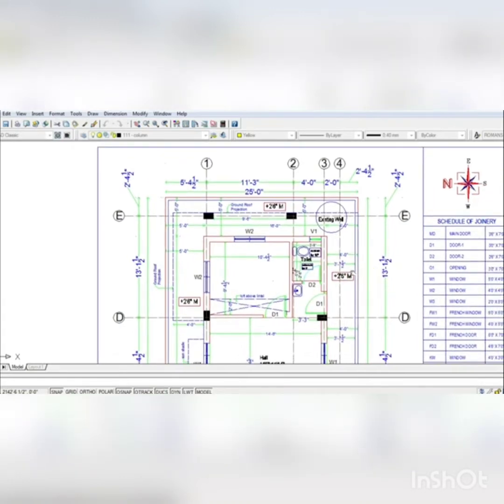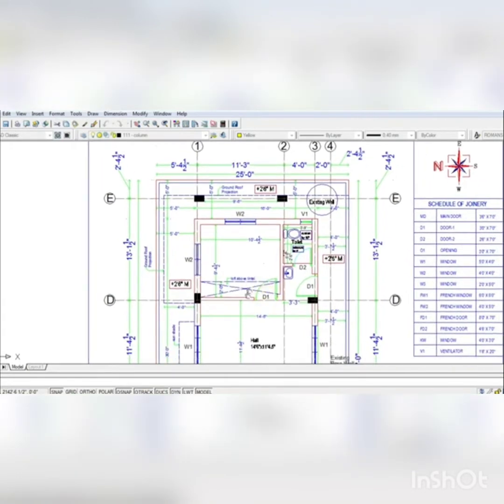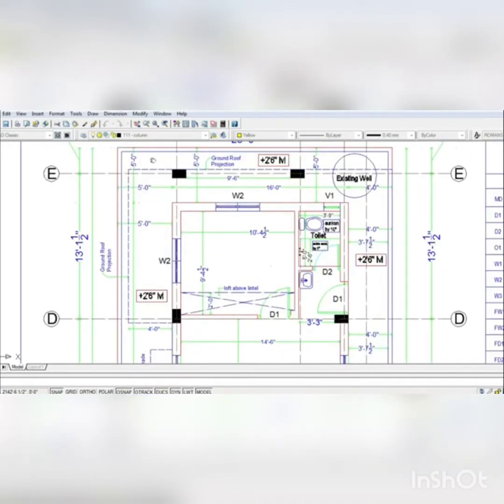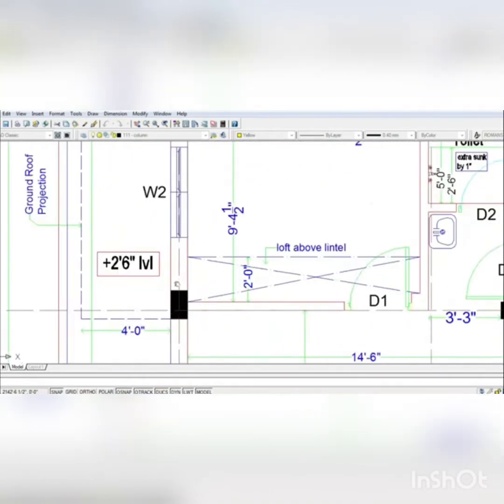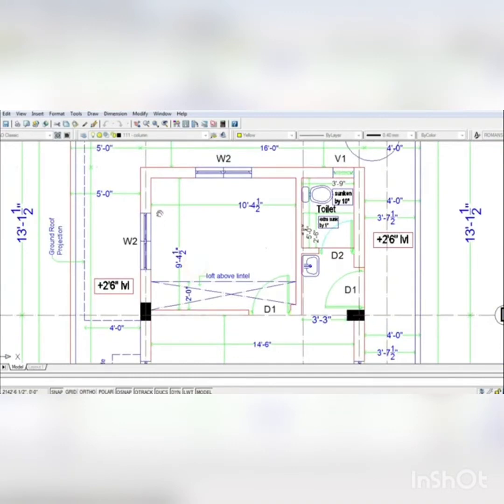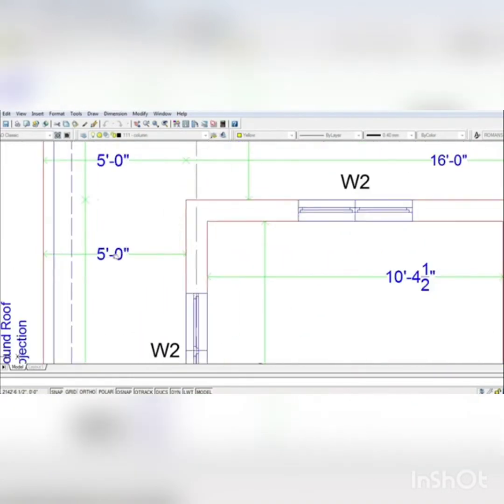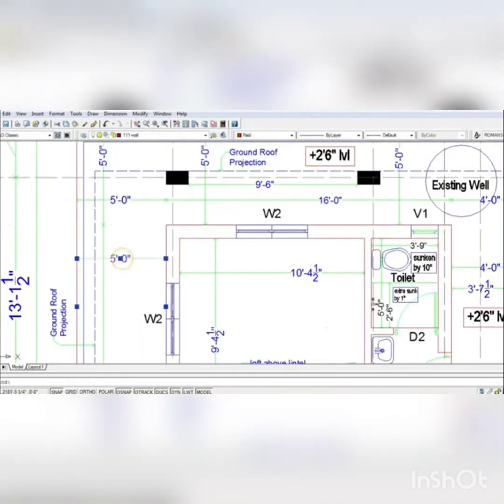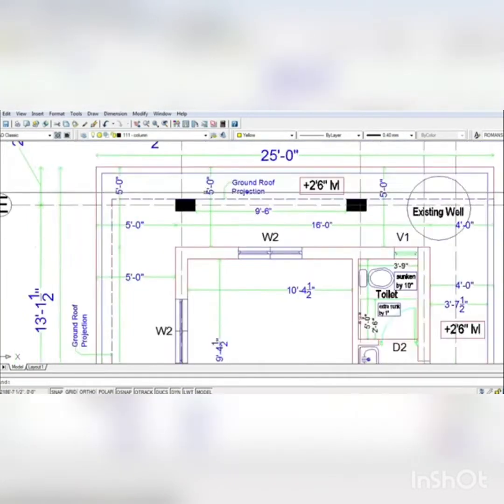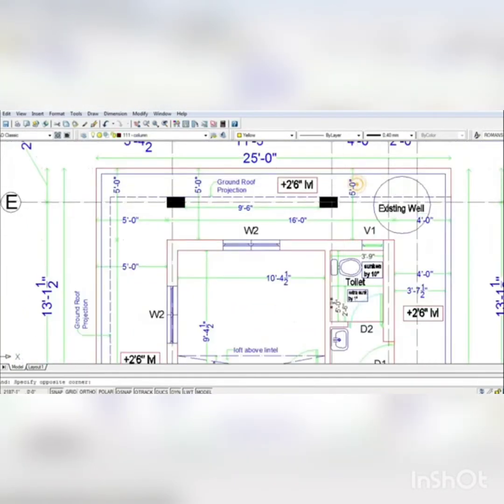In a floor plan, the centerline drawing has to be placed aligning the walls. After the centerline drawings have been placed, they are marked and the setbacks are clearly mentioned so that it helps to locate the columns on the sides.